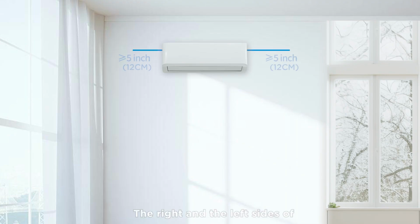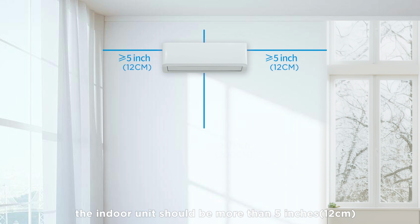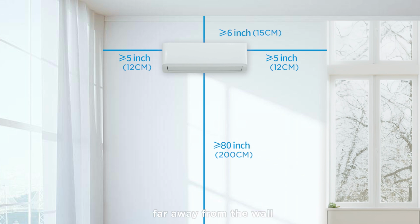The right and the left sides of the indoor unit should be more than 5 inches (12 centimeters) far away from the wall. The upper side should be more than 6 inches (15 centimeters) from the ceiling, and the lower side should be more than 80 inches (200 centimeters) from the ground.